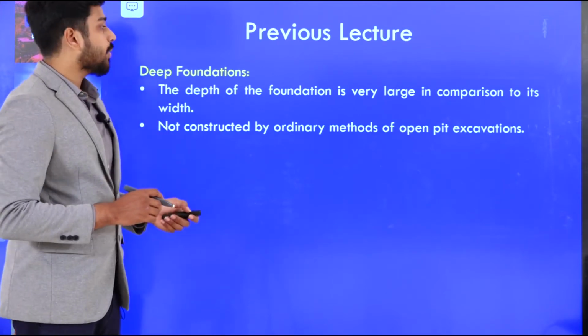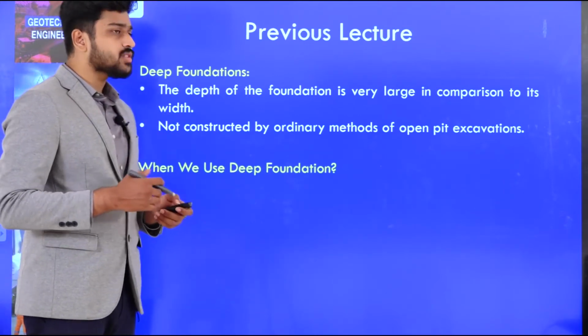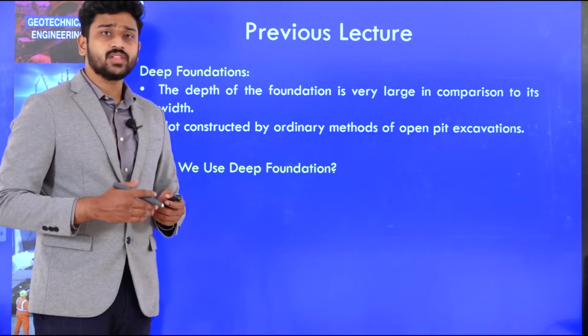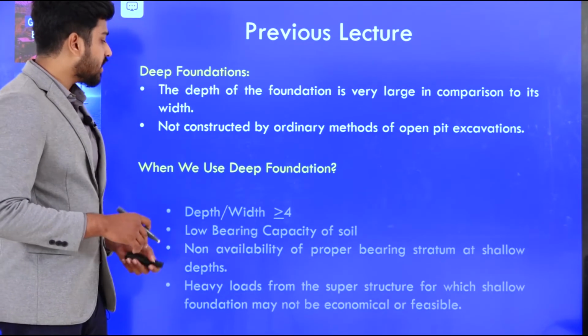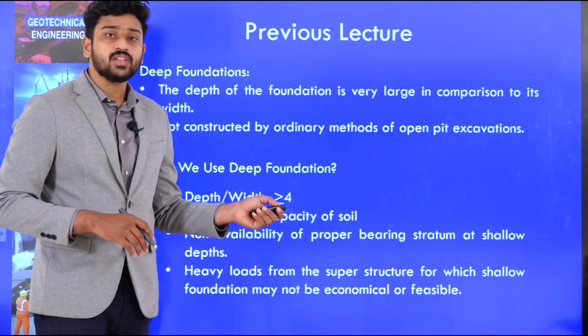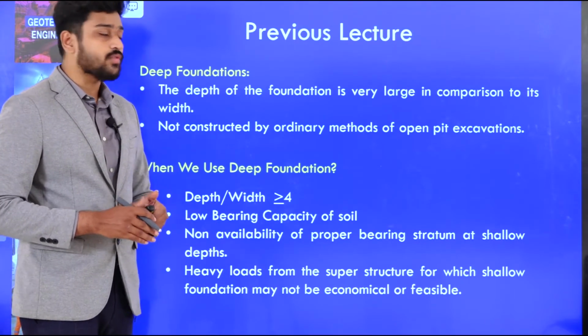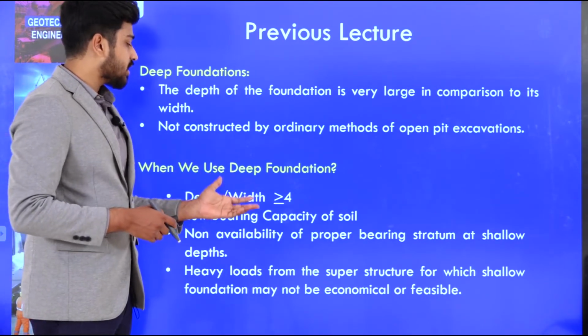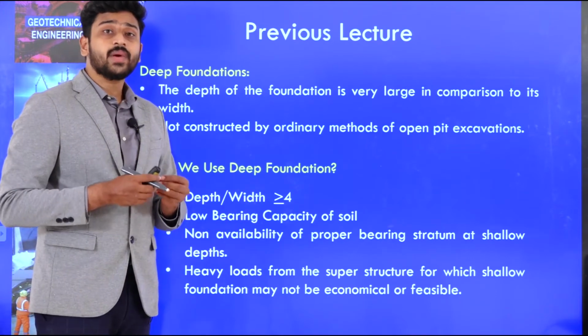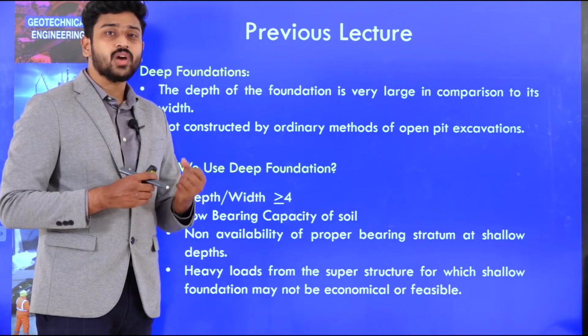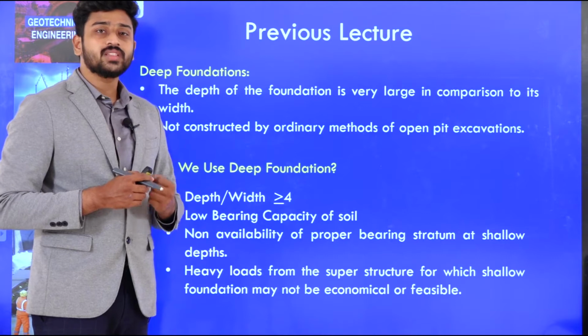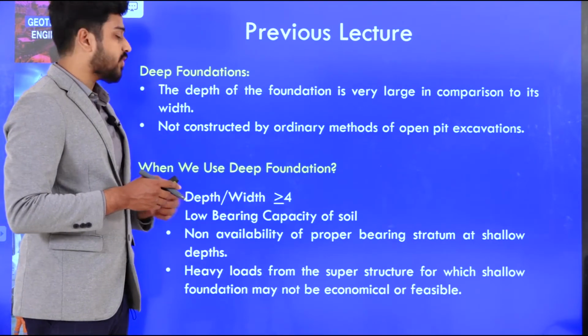Okay? Apart from that, why do we need to use these deep foundations, or when do we use them? When the depth to width ratio is generally greater than or equal to 4, we may go for a deep foundation. When the bearing capacity of the soil, that means the strength of the soil, is very low, in such a case also we will go for deep foundations.